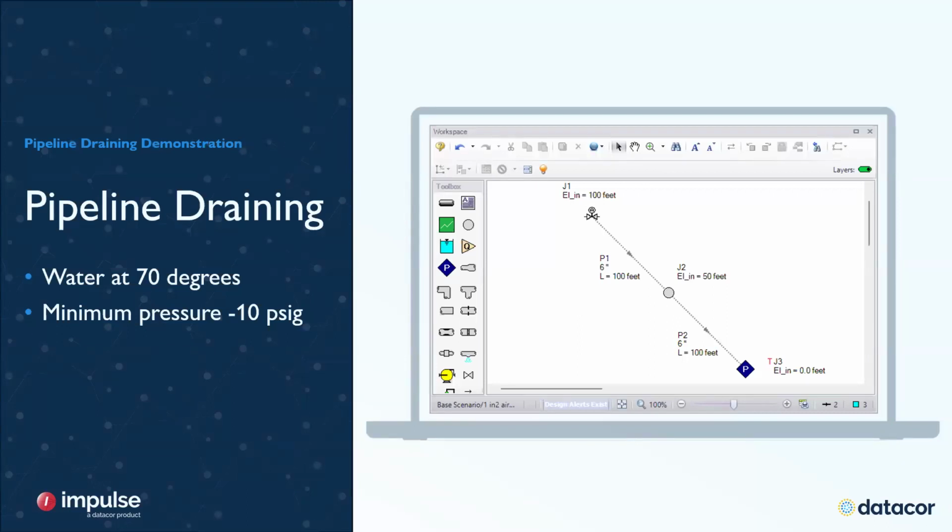So this is meant to model your typical pipeline situation, especially for downhill pipes, where you can place a vacuum breaker at a high point to let air in to avoid the pipeline crushing from the pressure difference. These siphon events can happen from an upstream pump trip or a valve closure, or maybe there's an equipment failure downstream, such as a leak or a control valve failure. But if the pressure in the pipe is too low, the pressure difference with the atmosphere will actually crush the pipe. So for this example, we're modeling the latter, where it's failing downstream, maybe a control valve failing or a leak.